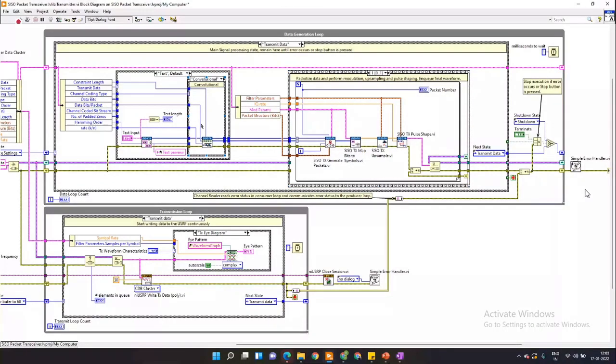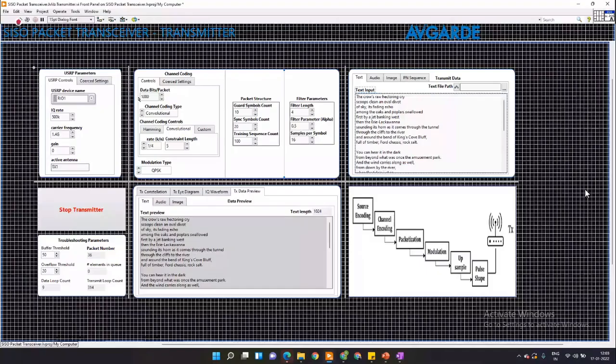After that, we do our coding over here. We typically prefer convolutional encoding because it gives us better data output. The faithfulness of your signal is better over here. So after this, we do a packetization over here. We generate packets, meaning we firstly split the data, if it's 10,000 bits, into sections of 1,000 because that is what I've defined over here.